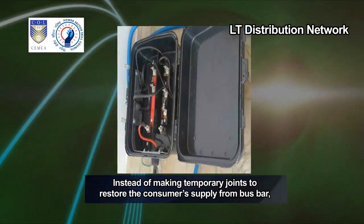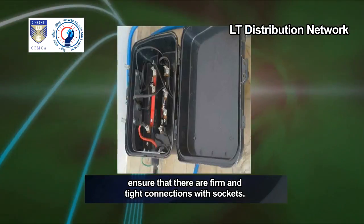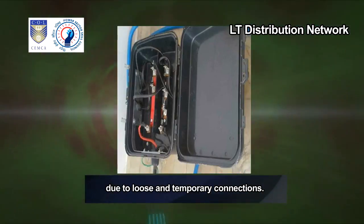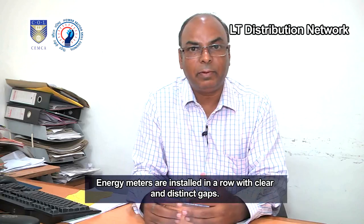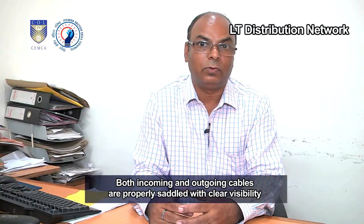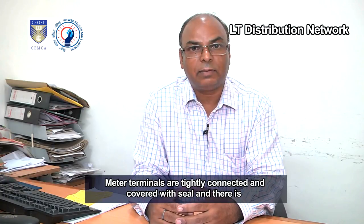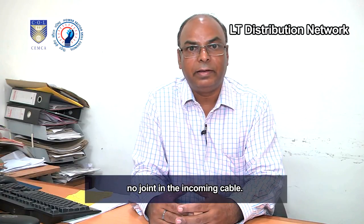Instead of making temporary joints to restore the consumer's supply from bus bar, ensure that there are firm and tight connections with sockets. There should be no jumbling of wires, which is major cause for breakdowns due to loose and temporary connections. The following are the corrective measures. Energy meters are installed in a row with clear and distinct gaps. Both incoming and outgoing cables are properly saddled with clear visibility from their feeding points. Meter terminals are tightly connected and covered with seal, and there is no joint in the incoming cable.